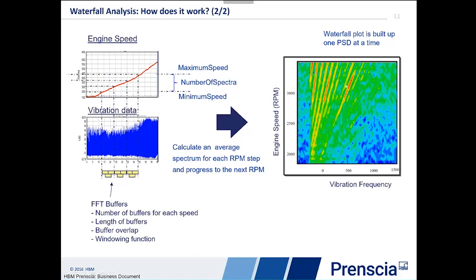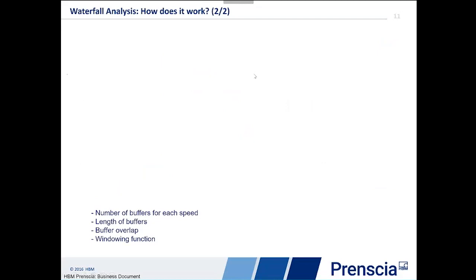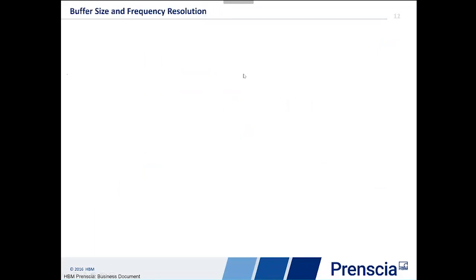the harmonic number, right? So we expect, again, for a four-stroke engine to have a line at twice the speed of the crankshaft. Plus its harmonics, because it's never a perfect sine. It's an explosion, so it's a burst, and you'll have loads of harmonics. So we expect the fourth order, etc. So I guess you're all familiar with that.